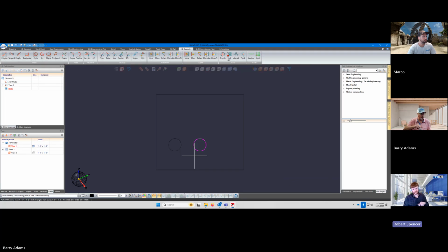All right, so use what you've learned here to draw one remaining half-inch circle, and then do 3/4 inch circles up top in a different location. Oh, all I did was click on it, and I never escaped the command. Yeah, because it's using the same clone parameters that you've already arranged, so you can keep going until you don't want to copy anymore or you need to change the copy parameters. Gotcha. I want to copy one more and then delete the one more.